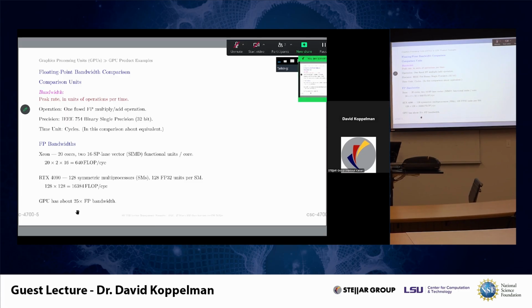In dynamically scheduled CPUs, which includes most of what you have, in your pocket, in my laptop, instead the load and the instructions that depend upon it wait around, but other instructions proceed. It's referred to as dynamic scheduling, and it allows instructions to execute when their operands become ready, as opposed to executing in program order. Executing in program order is easy and it's always correct, but doing so will cause the system to stall when one instruction does not finish fast enough.